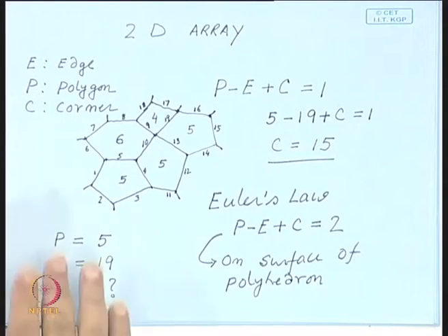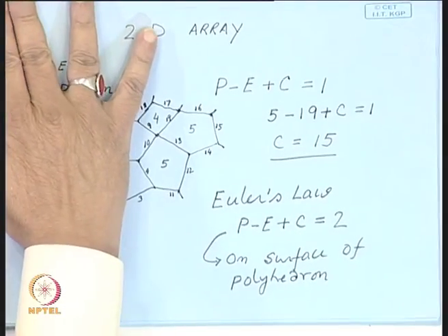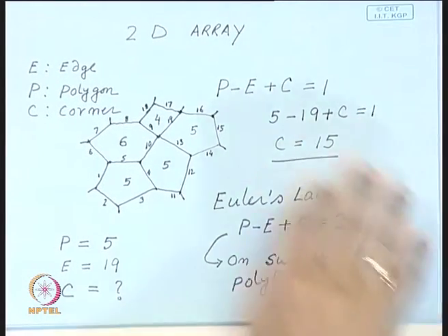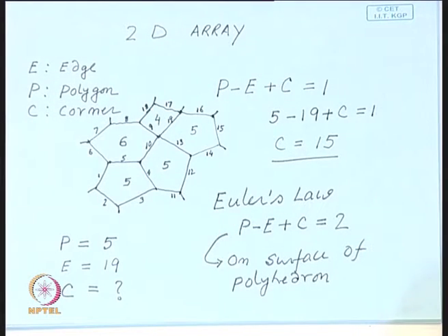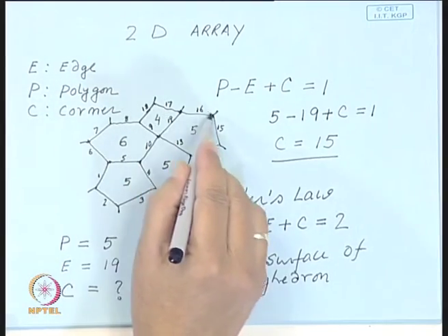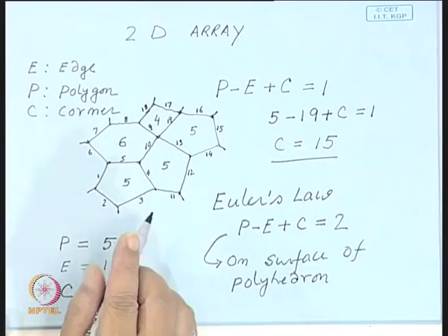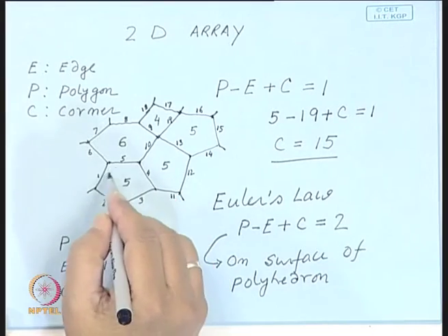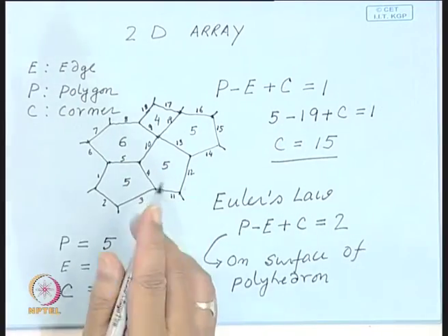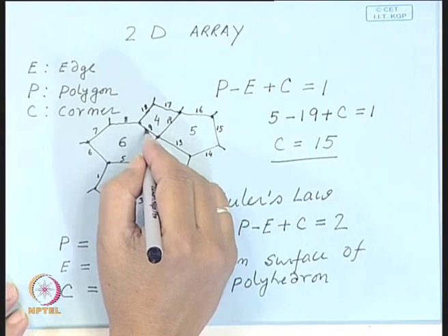And it will be interesting to also look at this array a little carefully, the 2D array if you try and fill up. And here is an example shown here. I have tried to put several polygons, each touching each other. So, this is a space filling 2D diagram, a space filling 2D array. Now, some have 5 faces, one has 6, another 4 over here. Now, when you pack them, you generate a number of edges where they meet each other. This is called grain boundary.